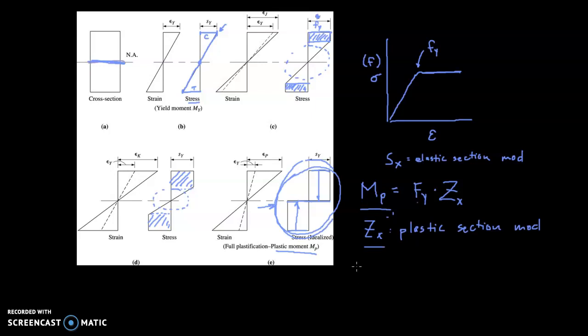Before we get to the actual example, let me point out that you wouldn't want to design a beam so that it actually reaches this pure plastic point. This is definitely failure. At this point, the beam develops what's called a plastic hinge. And if we've got our simply supported beam here, it would essentially develop a point in its midspan that does act like a hinge. So it would just begin to bend like that, real clearly in its middle.